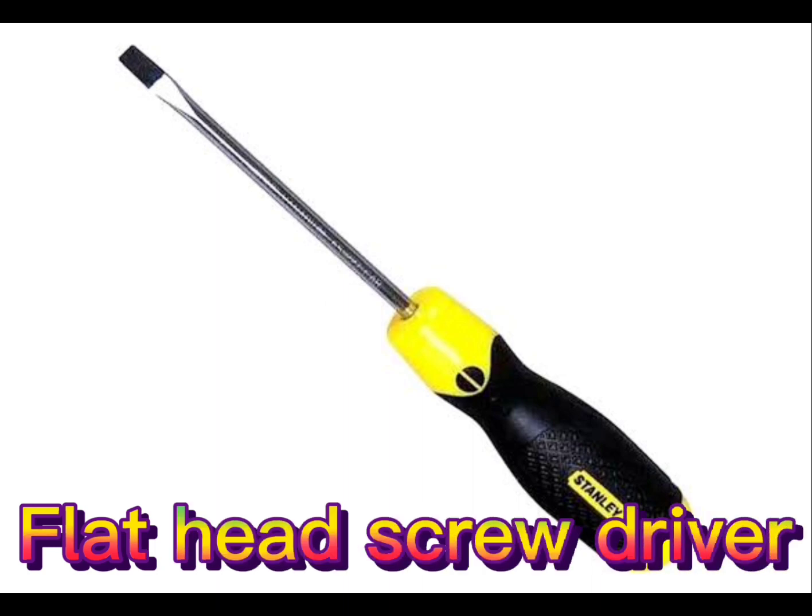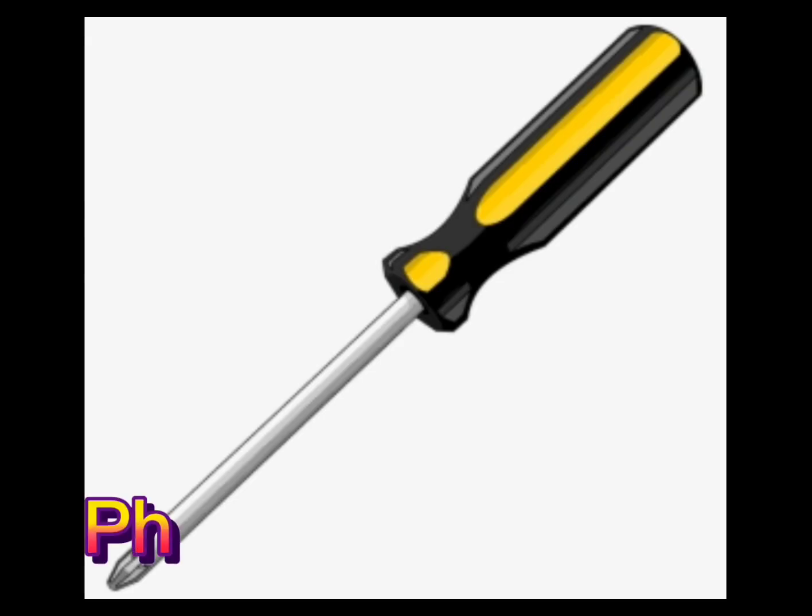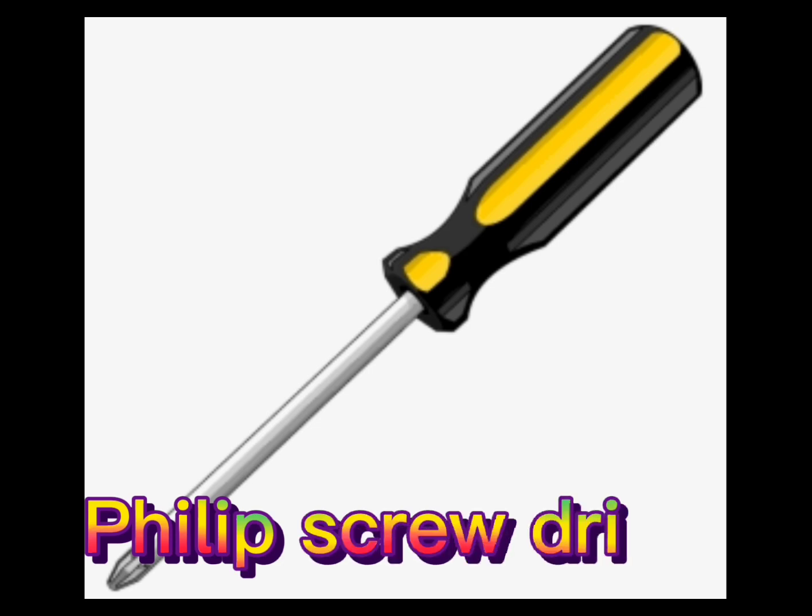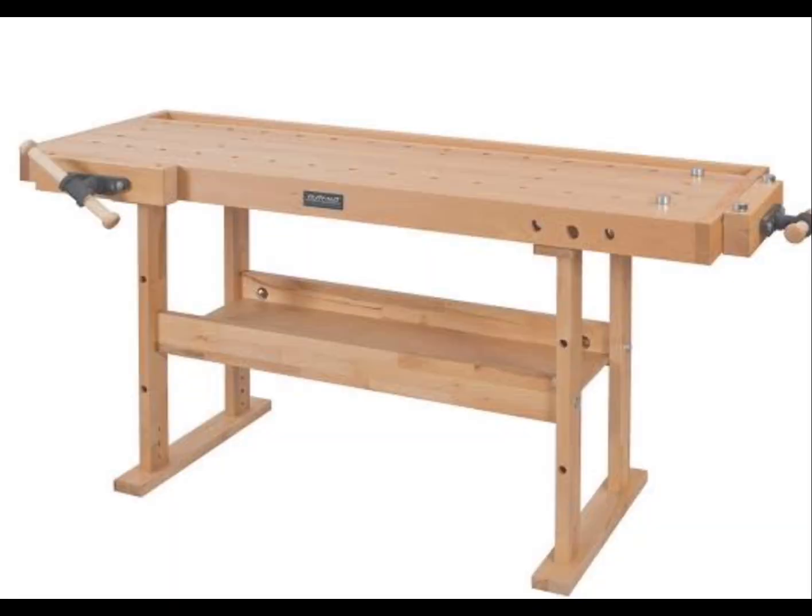Screwdriver. The blade end of the screwdriver should fit snugly into the slot of the screw. Otherwise, it may slip and damage the screw head as well as the surrounding wood. Flathead screwdriver is used in driving flathead screws. Phillips screwdriver is used in driving Phillips head screws.